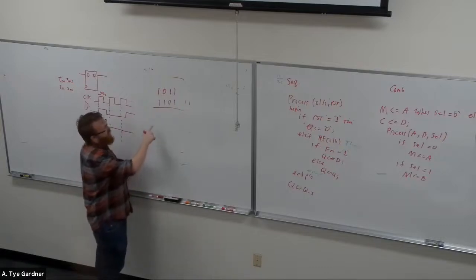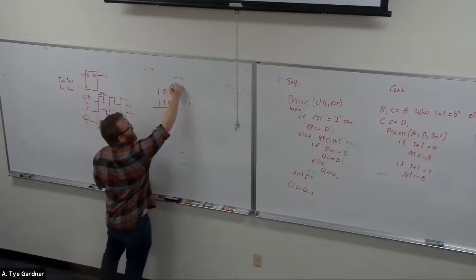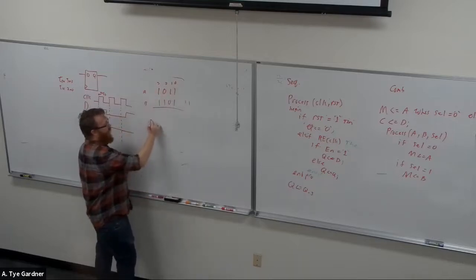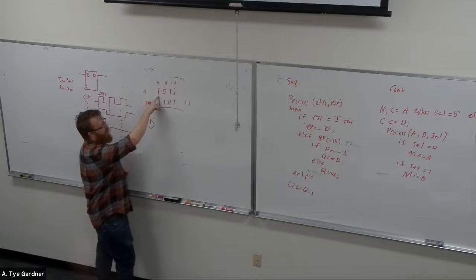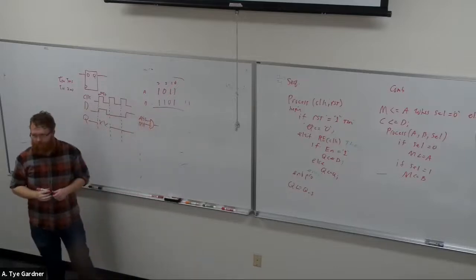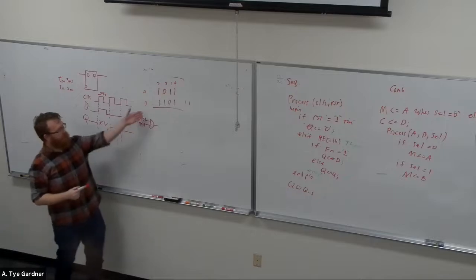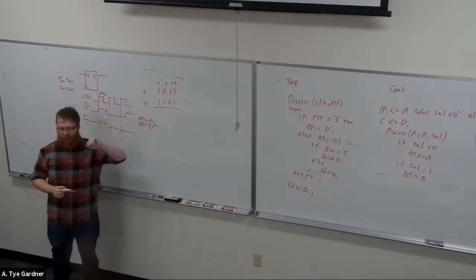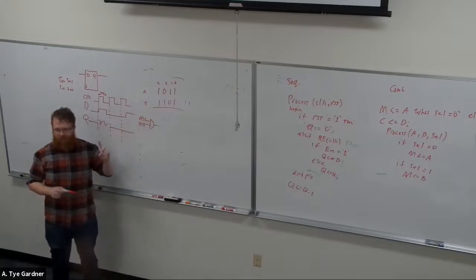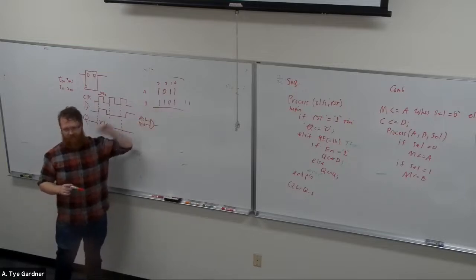A generate statement is literally just, so if I call this index 0, 1, 2, 3, and A, B, then the generate is pretty easy, right? Because you can just say, well, A at 3 and B at 3 is generated, right? It ends up being a little bit more complicated than that, but that's basically all the generate is doing: does this column generate a carry?